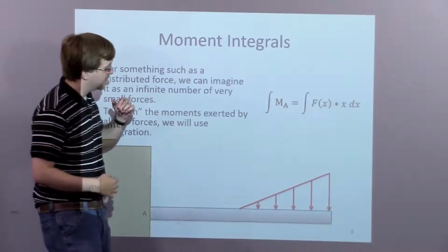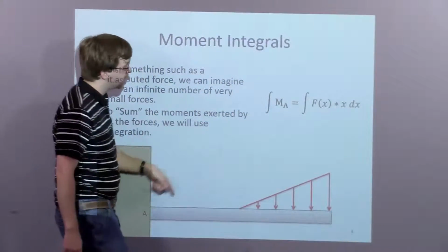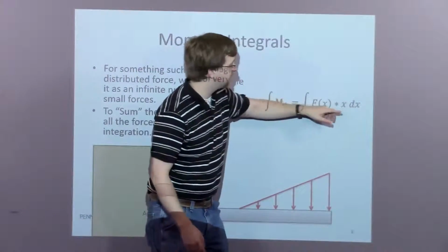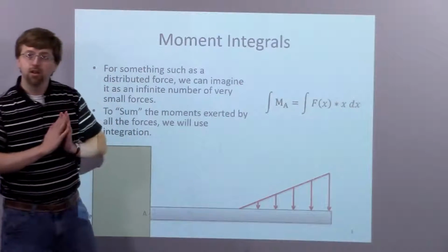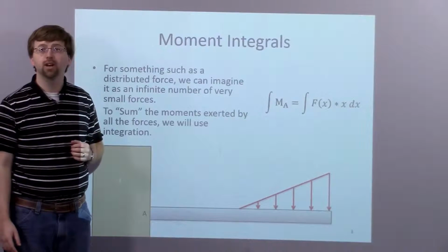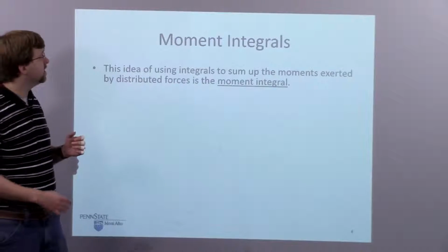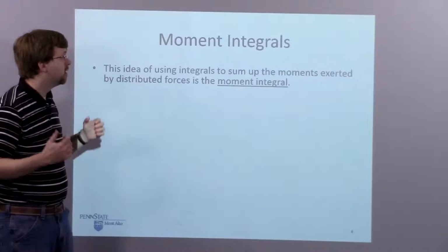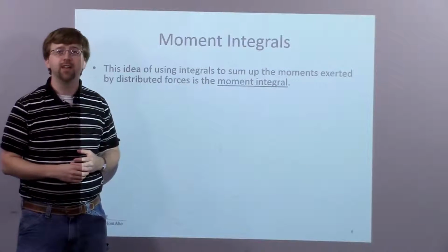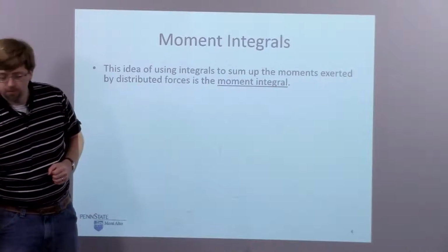And so our formula is the integral of all those moments about point A over here is going to be the force function times x. So force times distance, and I'm taking the moment by summing up all those pieces, which is what integration is for. Alright, so this idea of using integrals to sum up moments exerted by distributed forces, or very similar tactics for areas or masses, is known as the moment integral.